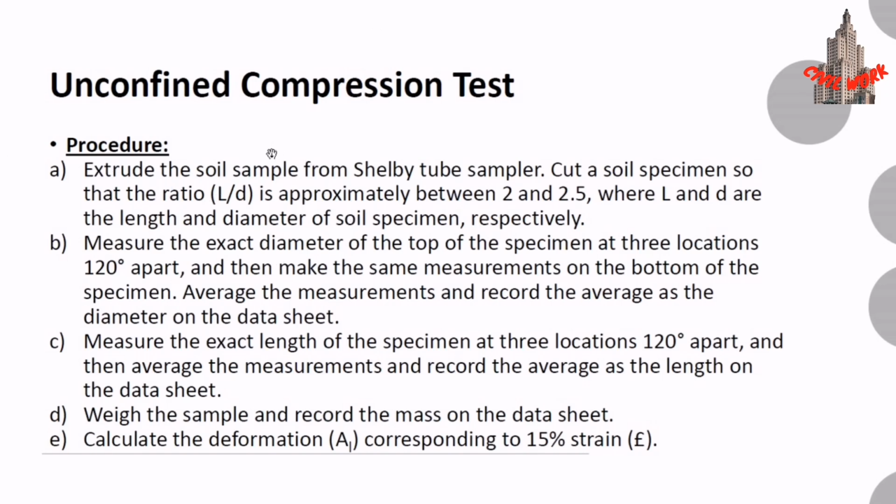First we have to determine the mold volume, which can be extracted by measuring the diameter and length. Usually we are given the diameter and length of the mold in which we have to make our sample. Then we have to calculate the total mass of the soil we have to take for making